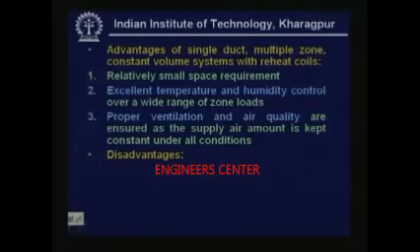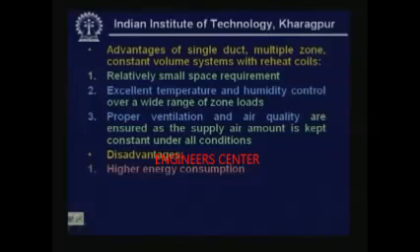However, these systems have certain disadvantages. They consume higher energy. Why do they consume higher energy? For example, in these reheat systems, if you are using it for summer, you have to cool and dehumidify the air to a minimum temperature so that it can take care of the maximum load. Now, if the load on a particular zone is not maximum, but only a part load, then this cold air is heated so that it can take the reduced load.